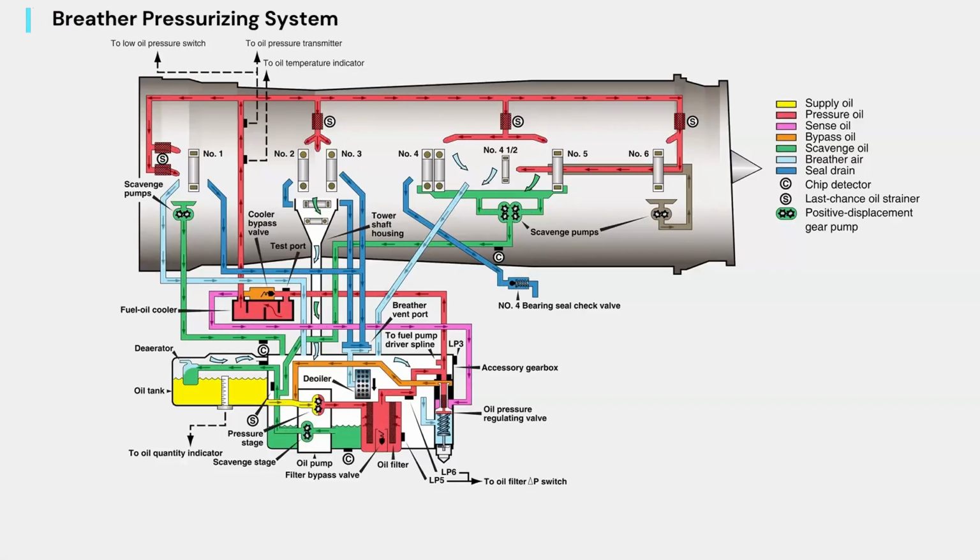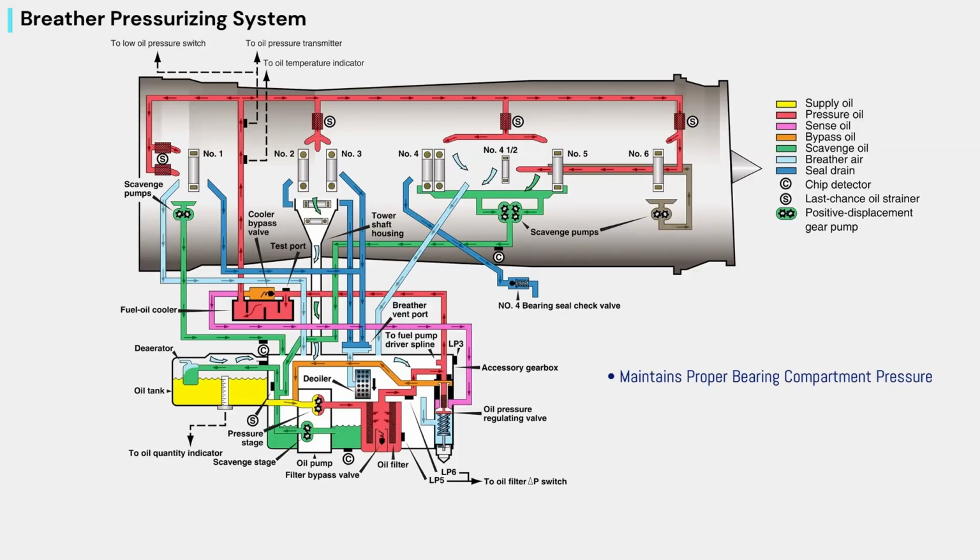The breather pressurizing system performs 2 important functions. First, it maintains the correct pressure inside the bearing compartments. Second, it helps create the proper oil spray pattern from the bearing nozzles.